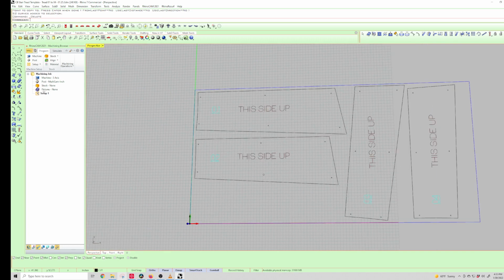So in this area right here, the first thing we want to do is come up to the machine operations or MOPS, and we want to create. We go to this other button here, click on that, and then that's going to give us a MOP set. So we want to click on that, and that's going to generate an area where we can have a single tool path, and then we can generate a separate MOP, or we can have a bunch within that area.